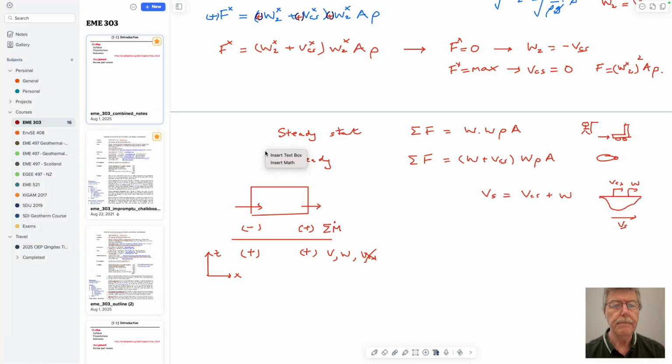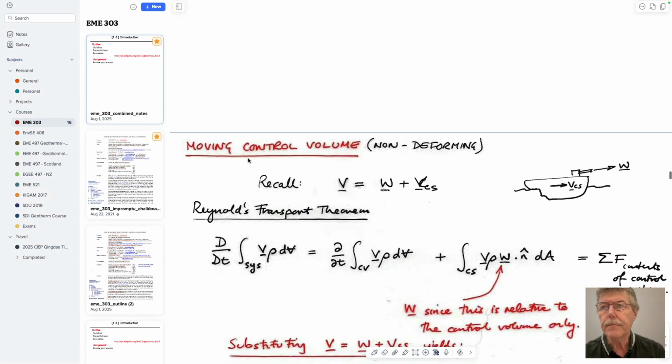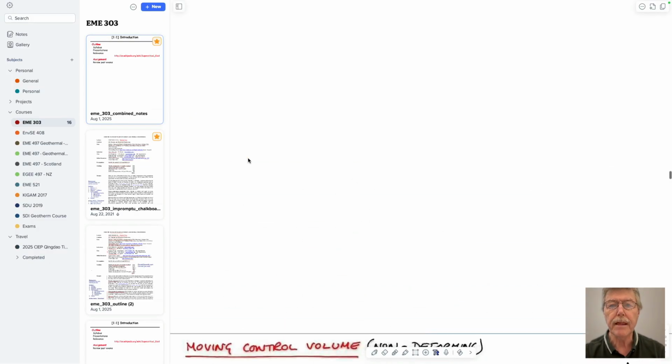From the video, would it be that the velocity would be basically found perpendicular to the face of the jet? The velocity would come out in the direction that the pipe is pointing, perpendicular to that area, and therefore if that was parallel to the direction of rotation, it would come out parallel. If it was at 90 degrees, it would go radially and have no rotational motion, right? You'd imagine that. We'll talk about that exactly today.